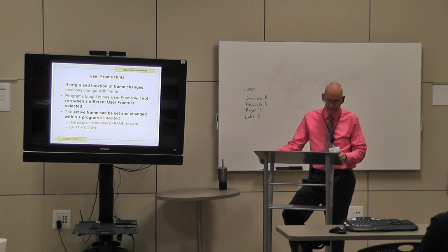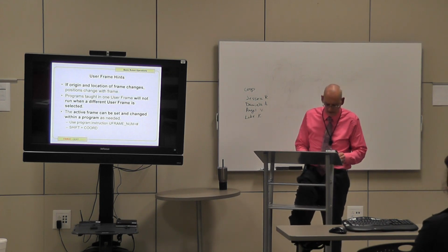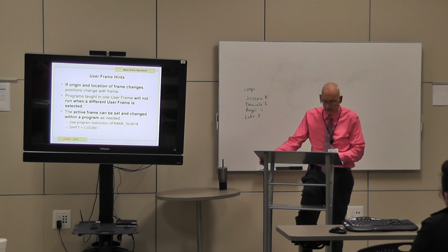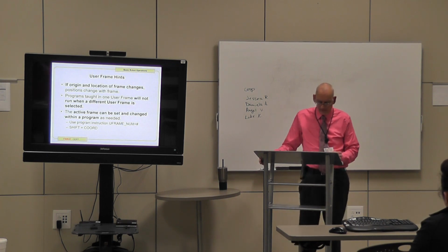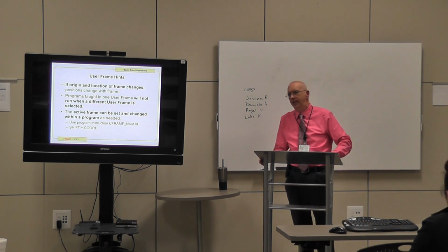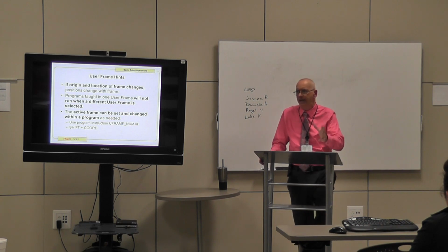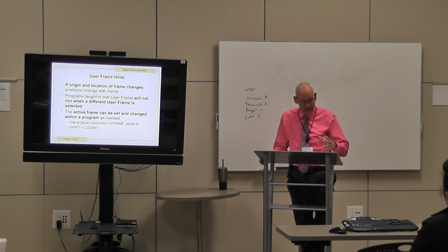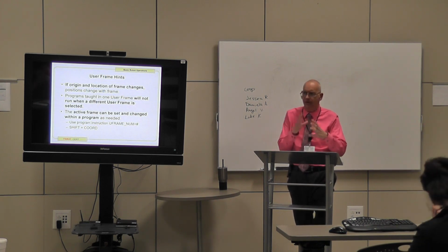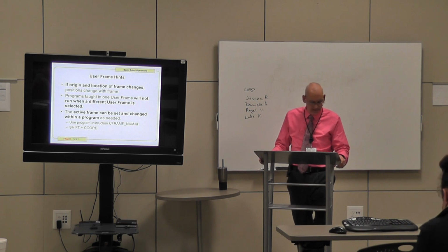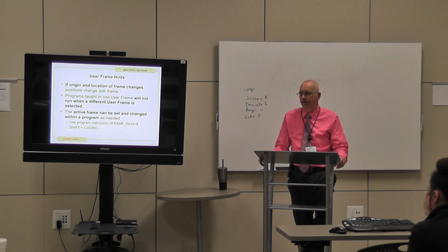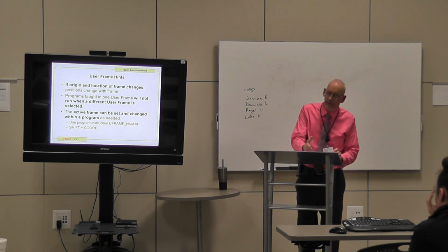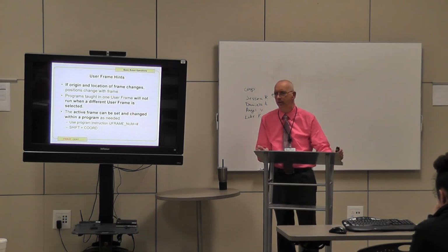User frame hints. These are some things you might want to understand and learn. If the origin and location of frames changes, positions change with the frame. So if we define that frame and we make changes to that, the positions are going to change with it. Okay? Programs taught in one user frame will not run when a different user frame is selected. Okay? You just can't do it. And it will be defined in your program what user frame you're going to be using.